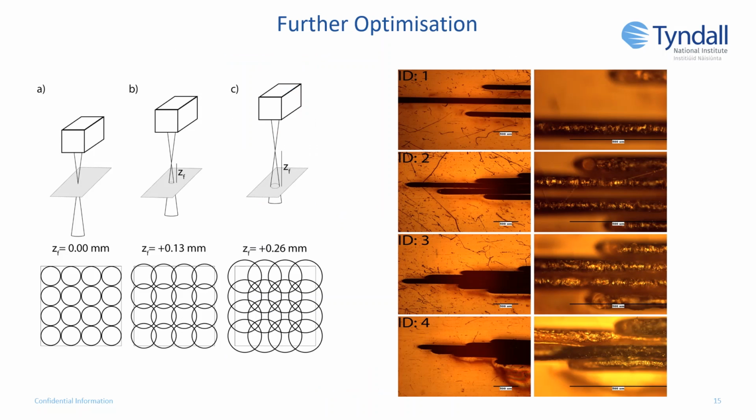Subsequent to the completion of the core parts of this work, we upgraded to a more complex CO2 laser system, which allowed the control of more than just laser power and scan speed, with parameters such as focal height adjustment, image density, so controlling the line-to-line overlap, and pixels per inch horizontal dot density. This system presented a similar but more complicated optimization problem than the initial hobbyist laser system. Despite this, the use of iterative design of experiments steps has demonstrated that we achieved equivalent parameters rapidly.